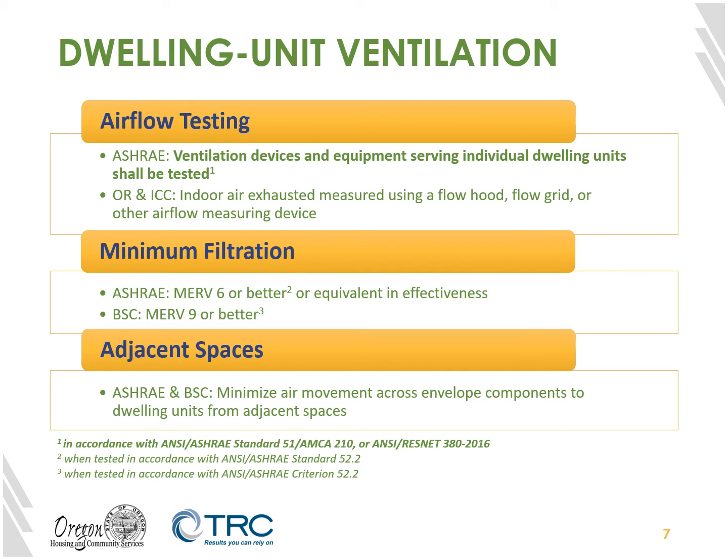Next up, airflow testing. ASHRAE stipulates that all devices serving individual units shall be tested, and it includes a detailed testing protocol using equipment such as a flow hood or flow grid. These standards also suggest filtration levels. ASHRAE requires MERV 6 or better, while Building Science Corporation recommends MERV 9 or better.